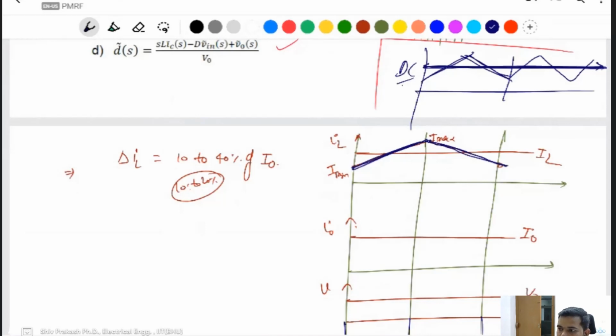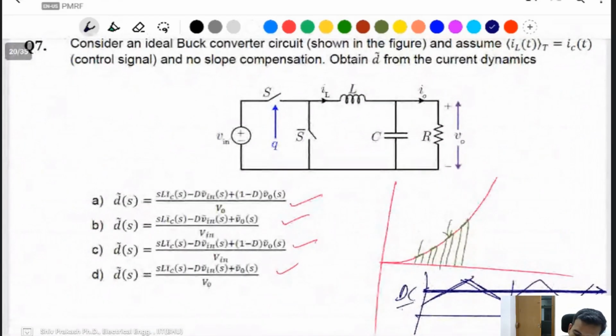If you are not working in a switching condition, imagine you apply a constant DC to the input and keep the switch connected all the time. Then the inductor acts like a short circuit in DC, and the capacitor acts like an open circuit in DC.